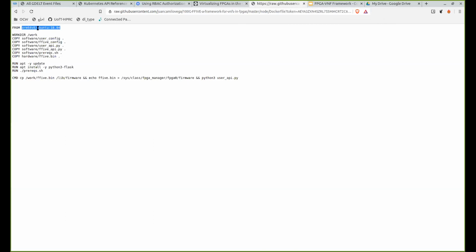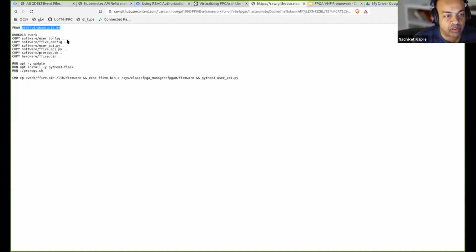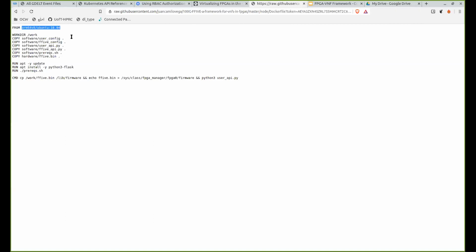I was testing. So how do you do memory mapping or sharing a memory region between the ARM and the FPGA? As long as we use AXI interfaces, we just have memory mapped interfaces. Those two programs are C++ programs. They access /dev/mem and use it to just allocate memory in specific locations, which are the memory mapped components.